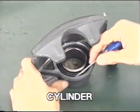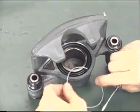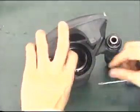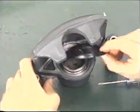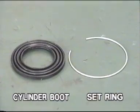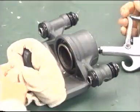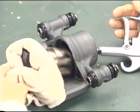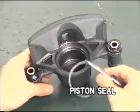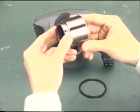Then disassemble the cylinder. Remove the set ring and the cylinder boot using a screwdriver. Put a piece of cloth or equivalent between the piston and the cylinder. Use compressed air to remove the piston from the cylinder. Do not place your fingers in front of the piston when using compressed air. Remove the piston seal using a screwdriver and the disassembling is completed.